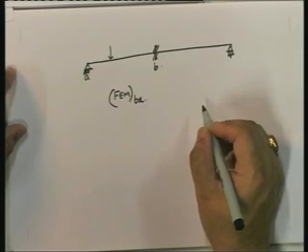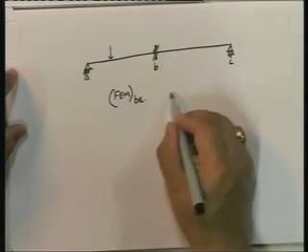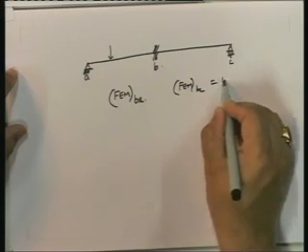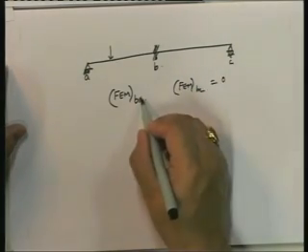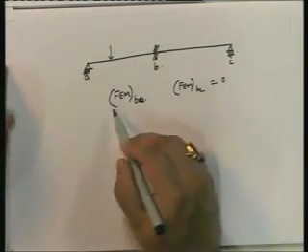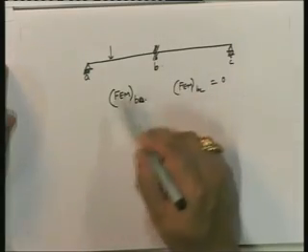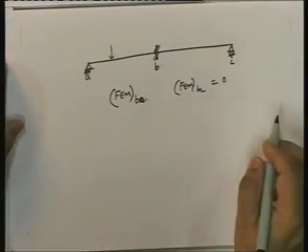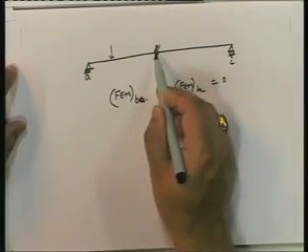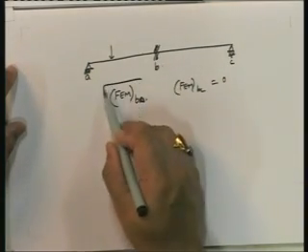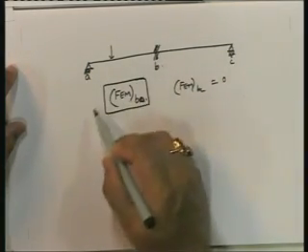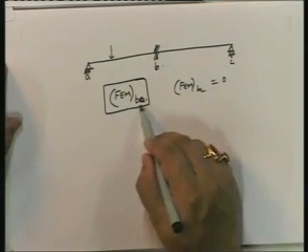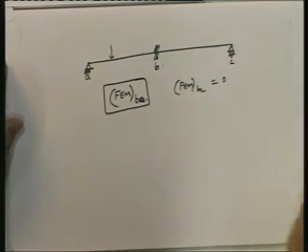And the fixed end moment at BC would be equal to 0. So you get a fixed end moment, and then what would you do? You would release it, you'd put this fixed end moment, find out, etc., etc. So while the member is between A and B, we could actually find out the bending moment at B by moment distribution, by first finding out fixed end moment at BA and then doing it.